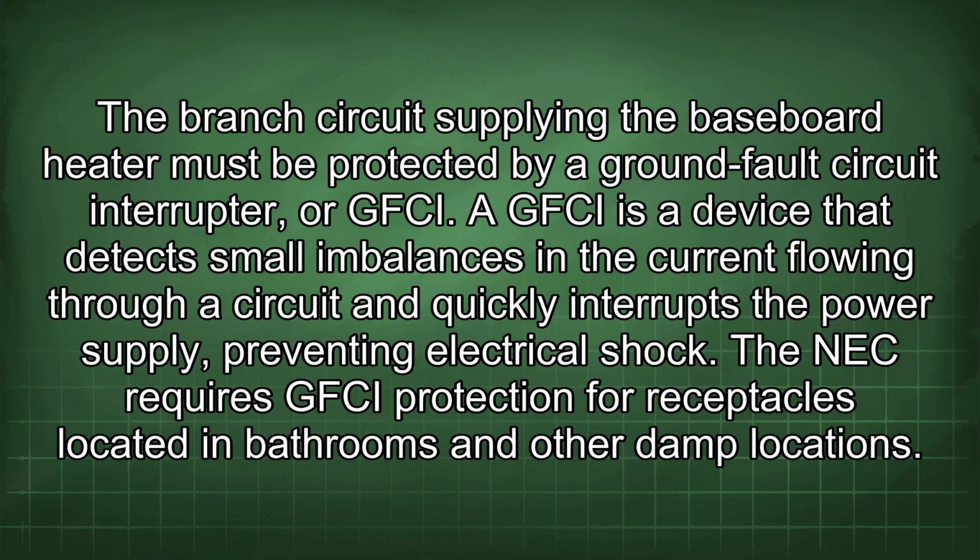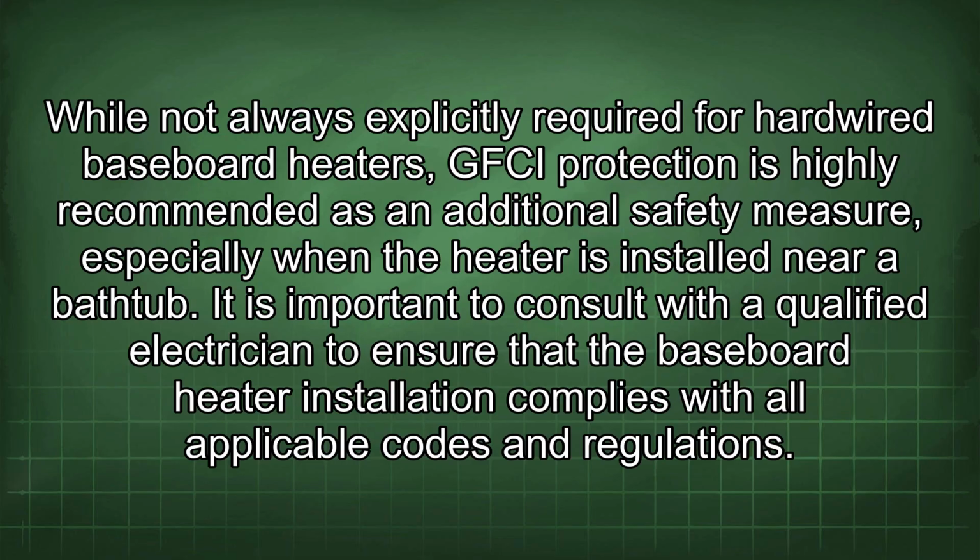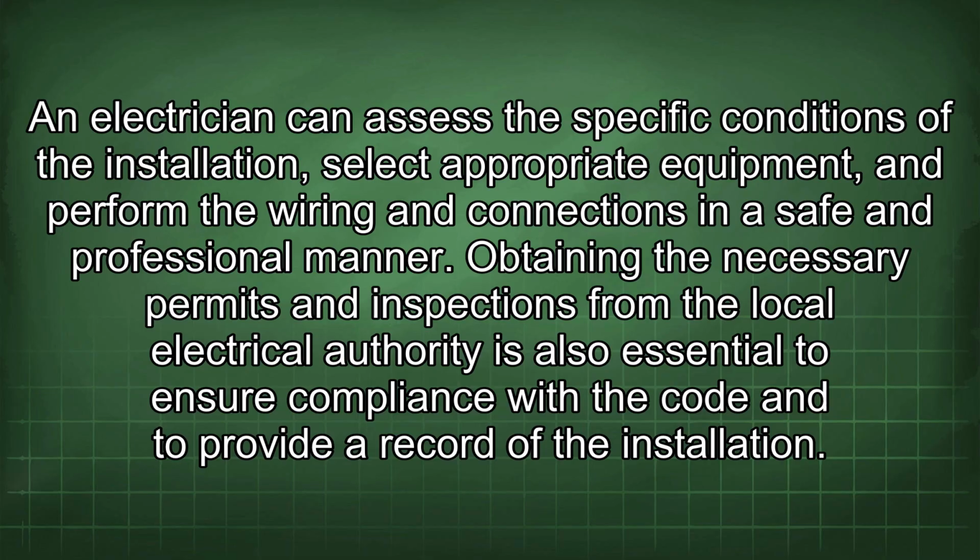The NEC requires GFCI protection for receptacles located in bathrooms and other damp locations. While not always explicitly required for hardwired baseboard heaters, GFCI protection is highly recommended as an additional safety measure, especially when the heater is installed near a bathtub. It is important to consult with a qualified electrician to ensure that the baseboard heater installation complies with all applicable codes and regulations. An electrician can assess the specific conditions of the installation, select appropriate equipment, and perform the wiring and connections in a safe and professional manner.